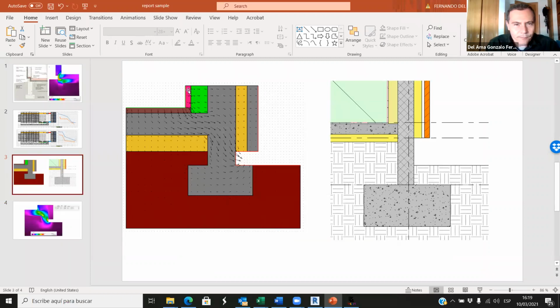Looking at this, in this line we have thermal insulation, concrete, another layer of thermal insulation. So that would be a high R value. If we go this way, this should be close to 30. But if we go this way, we don't have any thermal insulation. From this point to that point, we don't have any thermal insulation. So there are a lot of lines.